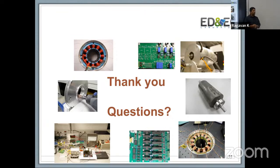Winding functions do require you to have at least some prior knowledge of the distribution that you have in the system. So yes, it is similar. You could actually use that using the available windings in the stator itself. But at the same time, you still have to take into account what you're measuring and the resolution of what you're getting. So the simple answer to your question is, it is possible to look at alternative methods, but at that point it was addressing a very specific need that we were trying to solve for the application. But your point is well taken.